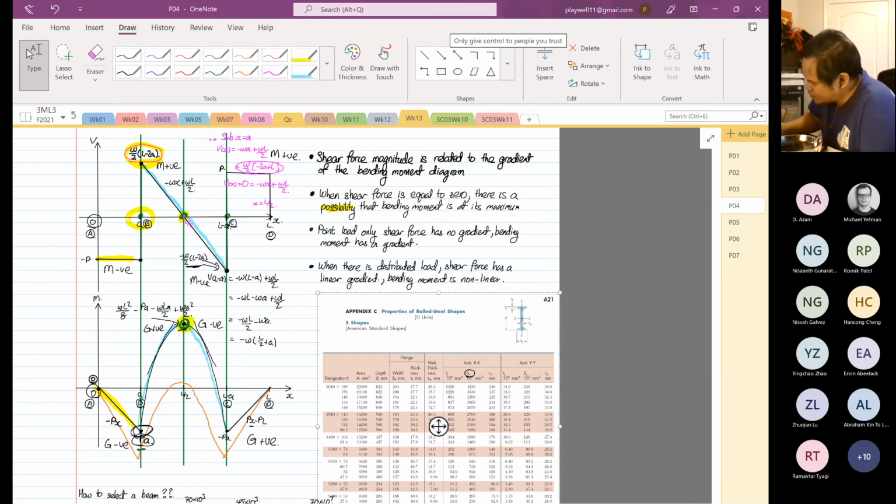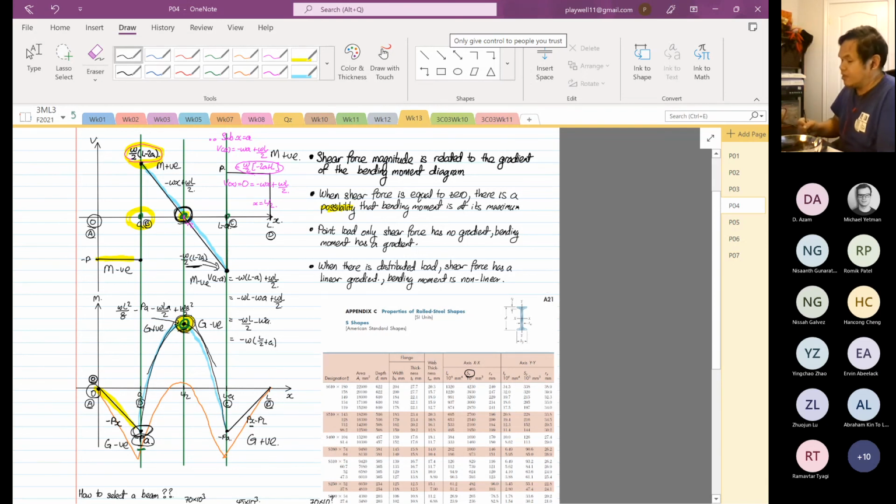This is because the shear stress is equal to 0, right? The normal stress is maximum. If we were to select point B or point C, then we have to use Mohr's circle. Okay, you have to be really careful down here. I'm not going to do it. Okay, relax. I have something else to teach you guys. We have to go back and plot Mohr's circle again. We have to calculate the shear stress and then we can calculate.